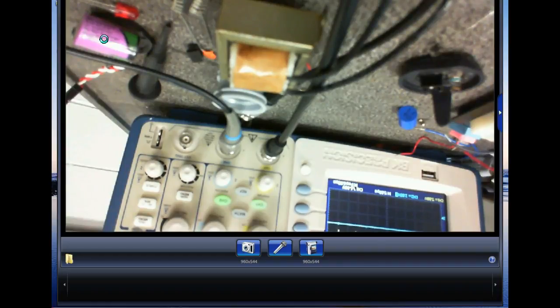But look at the charger for your cell phone. We call them little bricks, right? Little tiny things, but if you look at the current output, it's amazing, because they're switching power supplies. Now, they get warm, but they don't get hot. And why? Because those active elements are either on or off. And of course, what happens when that thing goes out? You throw it away. But that's the switching power supply. Ain't that neat though? It's real weird.